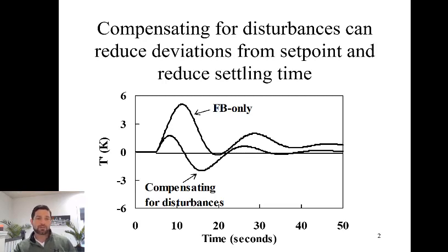This plot shows an example of how your control variable may change when you incorporate some type of feed-forward control. If we look at this first figure shown here, we have the process tuned in feedback control only. In feedback control you can see that the process changes by a decent amount, and then the controller starts taking a corrective action to bring the temperature back down to the set point, and then there's a little bit of oscillation in order to achieve the aggressiveness in response.